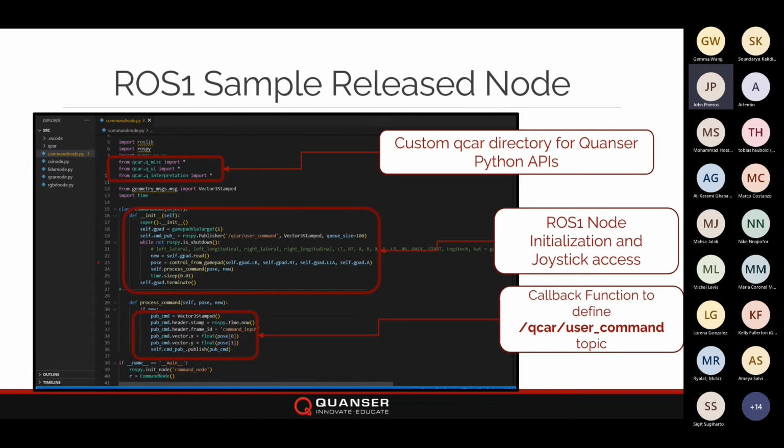The way that this is set up is mainly information gets published every time that ROS sees that there's a brand new command or sensor information from our joystick. So if we happen to read our joystick 100 times a second, then we're sending or publishing this information at 100 times a second.